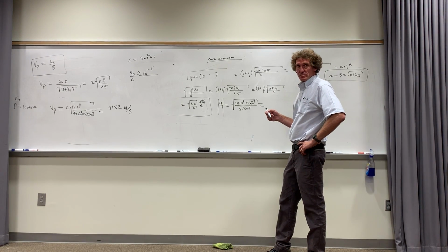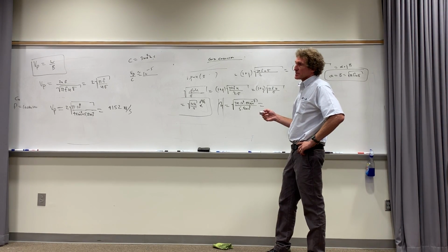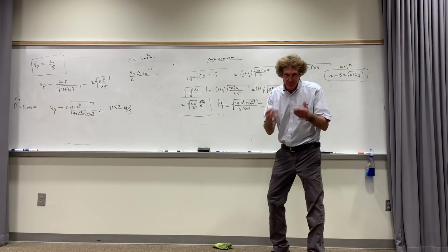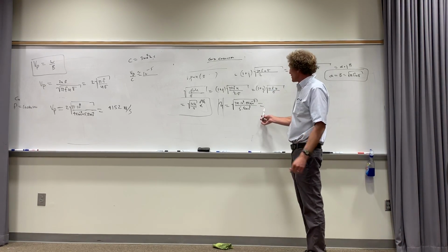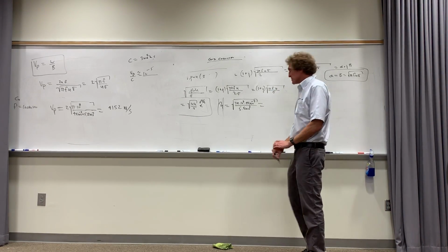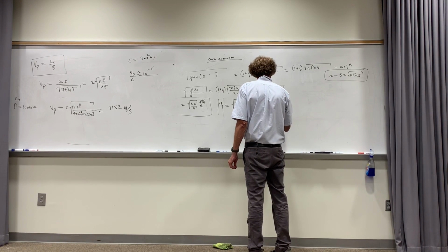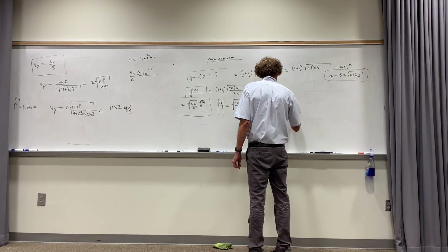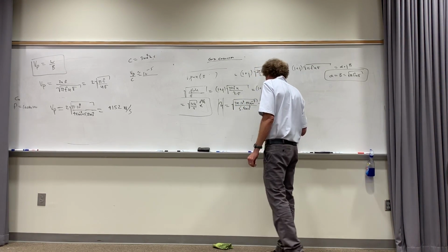Is this the intrinsic or characteristic impedance? Well, it's the intrinsic impedance of this media, not free space. So when you do it, what do you get for this? So 3.6 milliohms at an angle of 45 degrees, right?